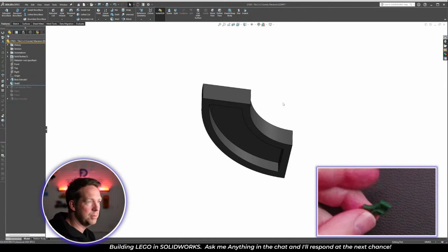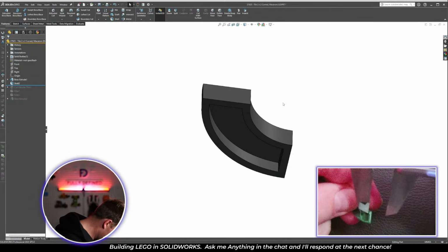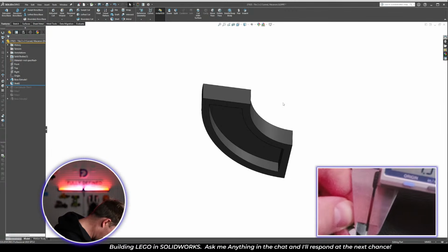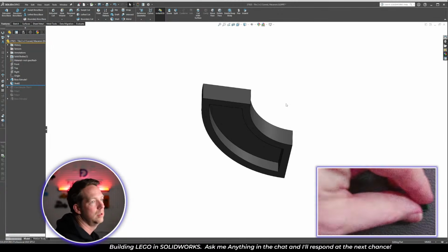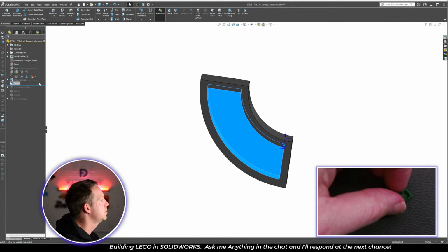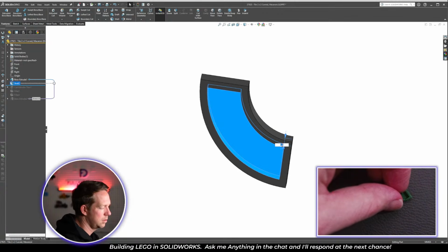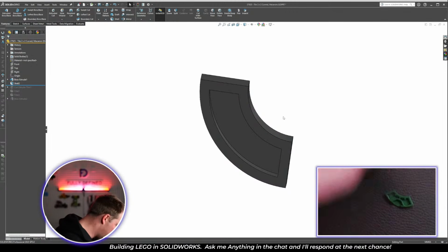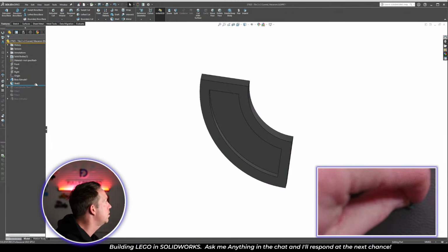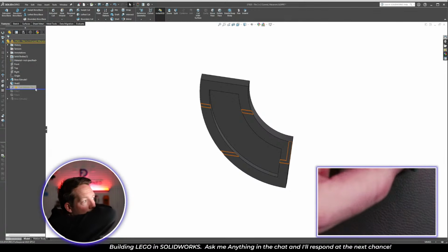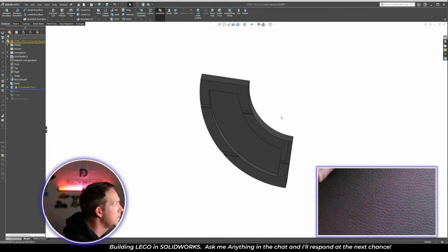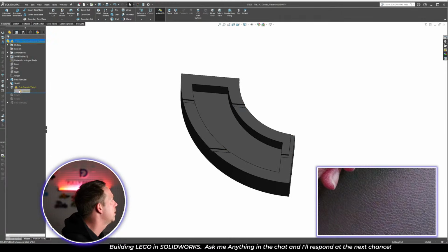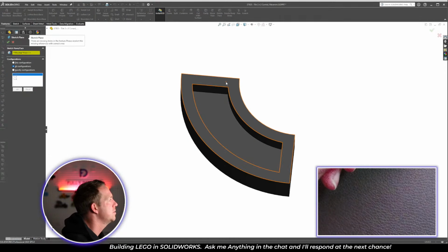And then do a quick measurement. And I think it's a bit thicker. 1.5 rather than 1.2. So we're going to increase the thickness. And then we can keep going with our detail. So roll down. We're going to update the sketch. And we probably have to update the sketch face as well. Yeah.